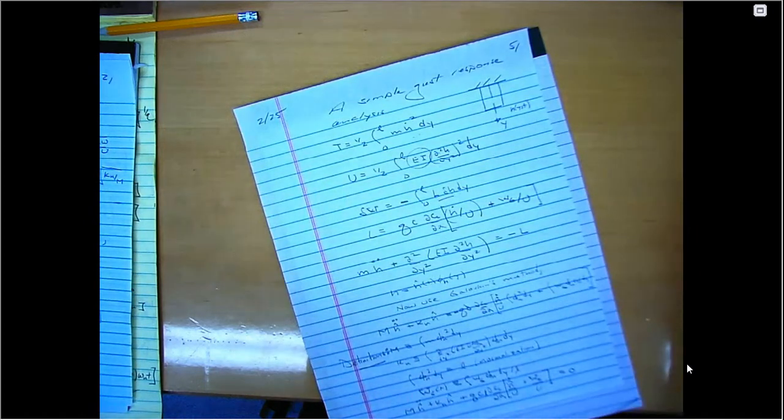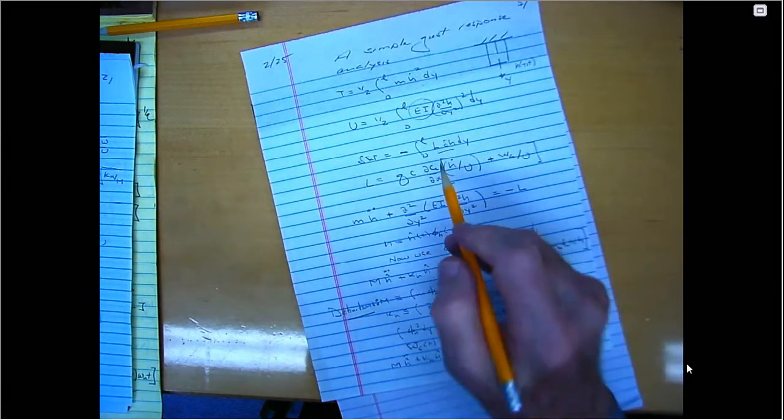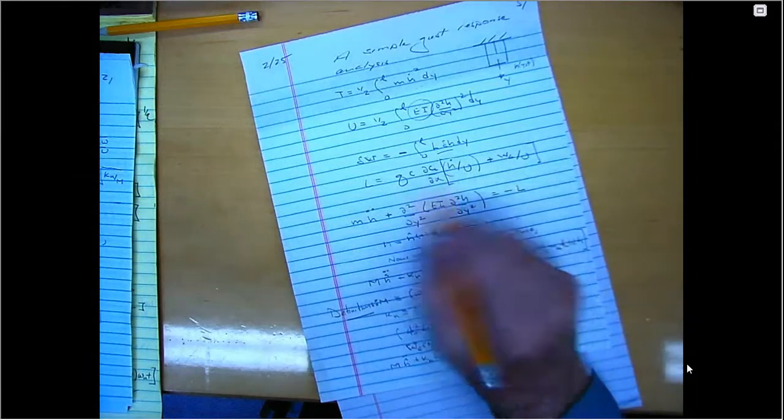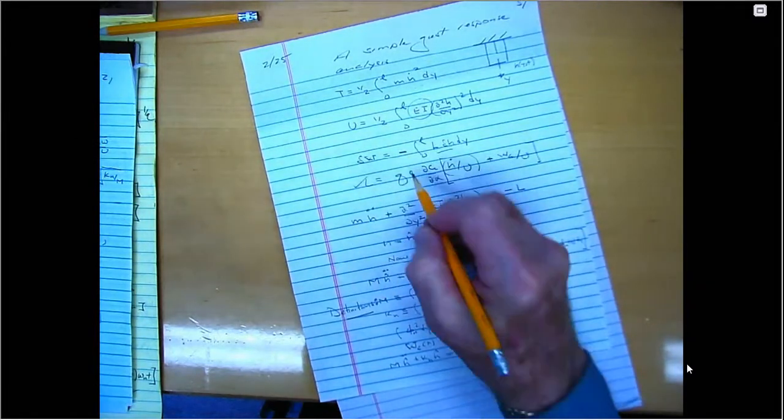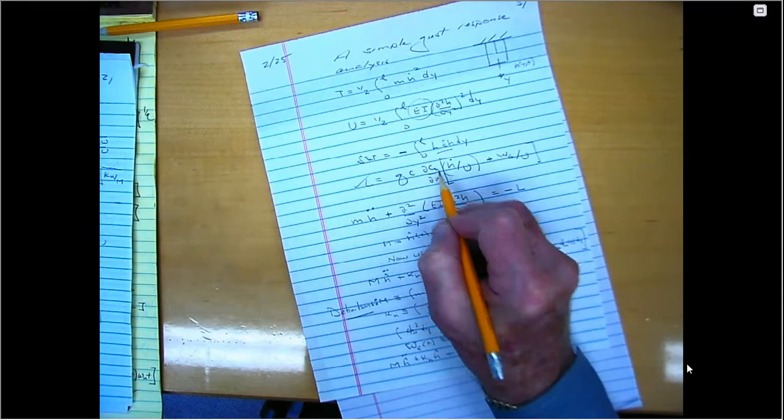because these aerodynamicists insist on defining the lift as positive up and the displacement as positive down. Only an aerodynamicist can do that. A structural engineer would never do that. But that's why aerodynamicists do it, and they're in charge, at least as far as lift is concerned. And the lift is given by q times c times dCl/dα